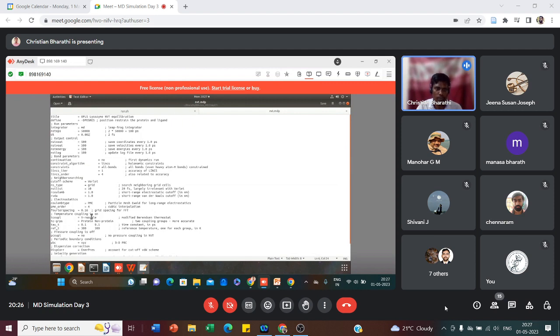And here we are doing temperature coupling. NVT is temperature coupling. We are applying one particular method, the V-rescale method. We are taking the protein atoms here. If you are using non-protein atoms, then we have to define the non-protein group. The reference temperature is 300 Kelvin. You can change your own temperature here as per your interest for MD. And periodic boundary conditions are in all directions.